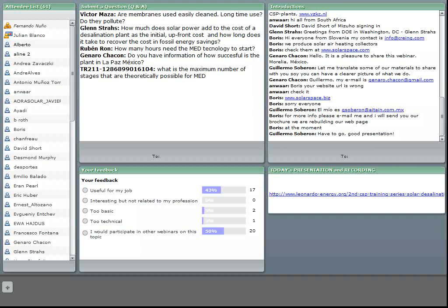So up to 70 Celsius we have a number of salts that, when deposited, make the scaling highly problematic, so we significantly reduce the pretreatment that is needed in the MED. So the upper limit for the MED is 70 Celsius, just to avoid this scaling and to reduce the pretreatment significantly. And from the lower side, the temperature is given by the ambient temperature that you have,